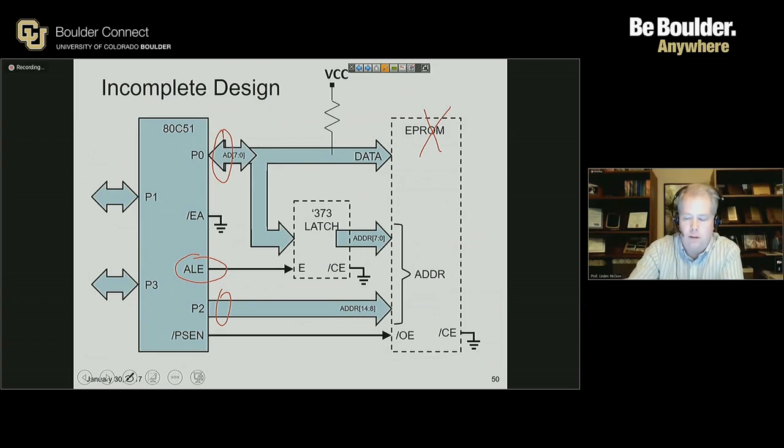There's no chip out here that's actually driving data back to it. So it reads its P0 value, and P0 is probably floating at something close to a 0 because that's what was just previously driven out of P0. So it reads back in a 0.